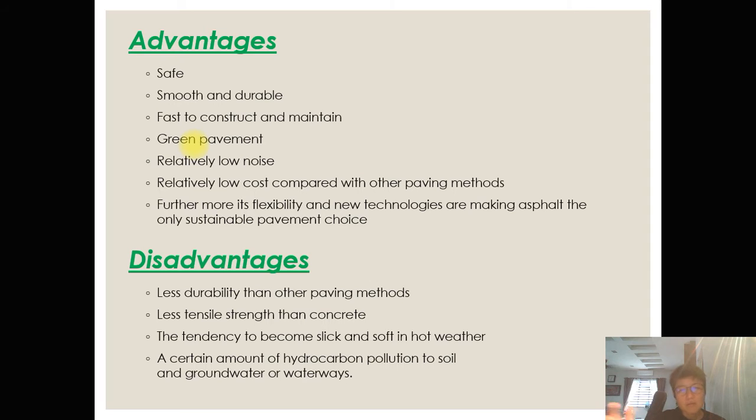So you do know that after a while, every road will need to be rehabilitated. So they actually scoop out the top layer. Essentially, they scoop out right down to just before the base course, and then they mix up again whatever is broken up, add some new stuff, and then put in the bitumen and retie it and recompact it. So there's little wastage there. So you could say it's going green.